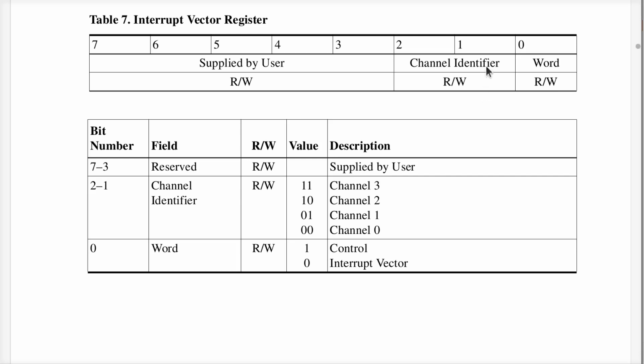Okay, and these 2 bits always represent the channel numbers. And because channel number 0 has a 0, 0 in here, this one also must be 0. Whenever you have a binary number that ends with 3 zeros, the rest of that number must be a multiple of 8. And that's where the multiple of 8 jazz comes in.